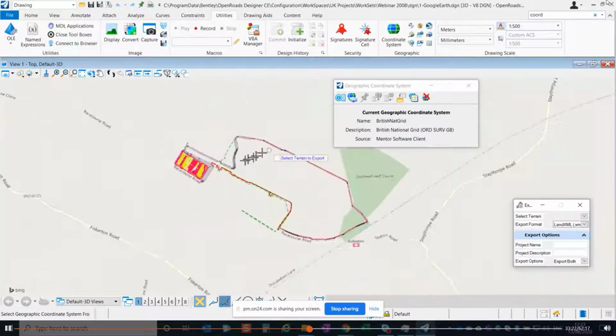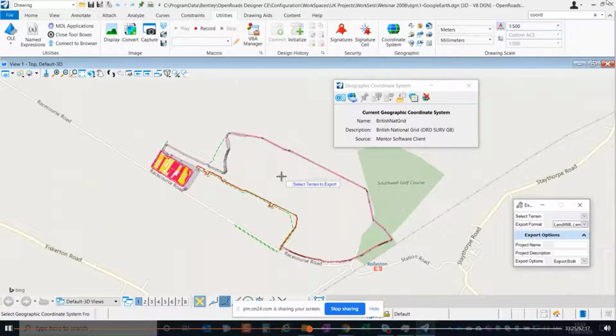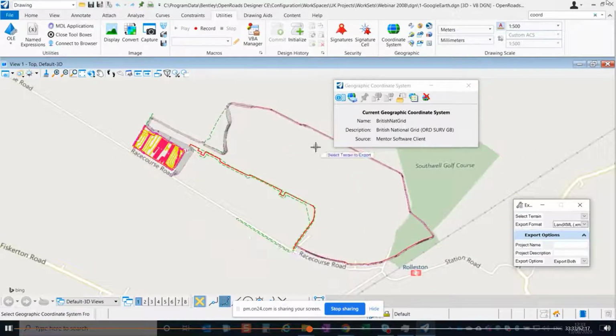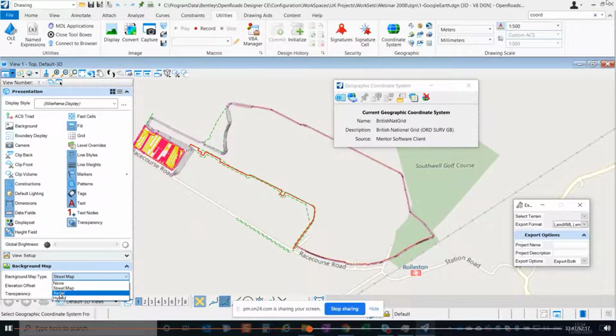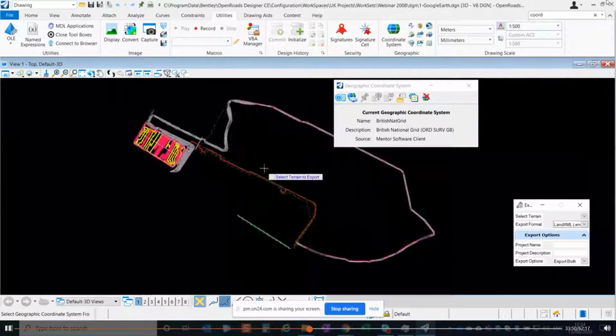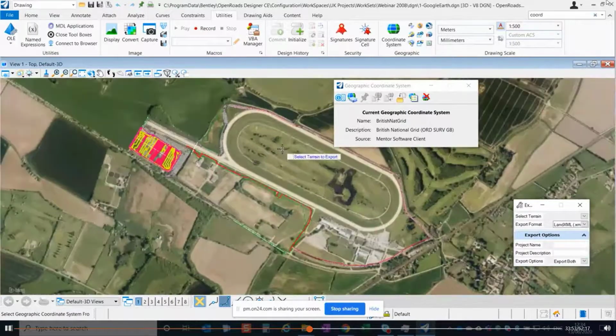Of course, Bing Maps is not as accurate as any orthophotos or any drone survey campaign. So it should be used just as an indication, a way to help you understand the context of your project, and not for the design. So you can have this as a background, as demonstrated here. You can use the aerial view if you want. The only thing to be aware of is that if you want to add it to your drawings, on your sheets, and have them printed, it won't work with this one.